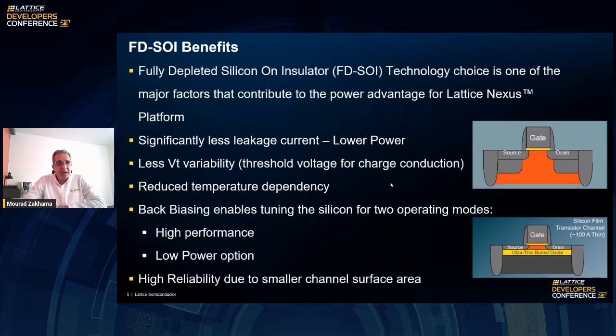So let's start with the FD-SOI. Fully depleted silicon on insulator, FD-SOI technology, is one of the major choices made by Lattice to architect their Nexus family, and it contributed a lot to bringing lower power FPGAs. What we notice is that with the shrink in process technology, static leakage current increases for each transistor and becomes a more significant portion of the overall power consumption.